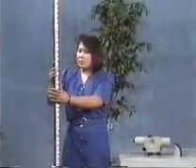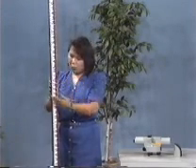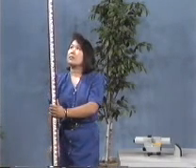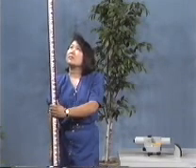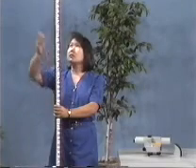The Philly rod is a 2-piece wooden rod with graduation marks in feet, tenths, and hundredths. Unextended, it can be read to a height of 7 feet. For heights greater than 7 feet, the additional section can be raised and clamped in place.